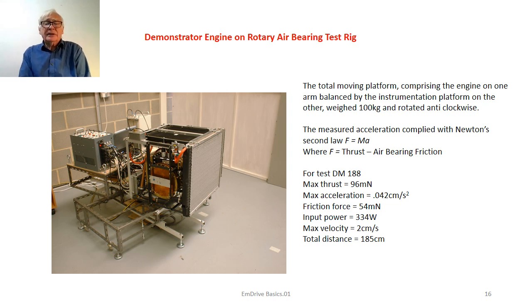The test results for the test that we quote fairly widely, which was number DM188, was a maximum thrust of 96 millinewtons, giving a maximum acceleration of 0.042 centimeters per second squared. Not a very large acceleration, but significant when you look at it over an acceleration period of a minute or so.